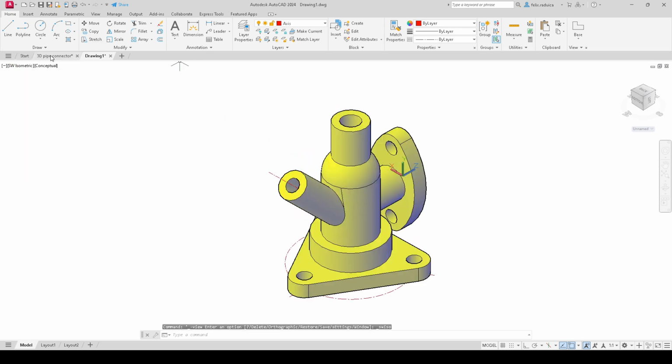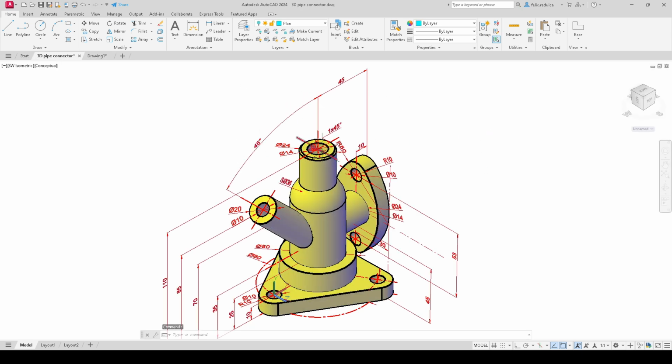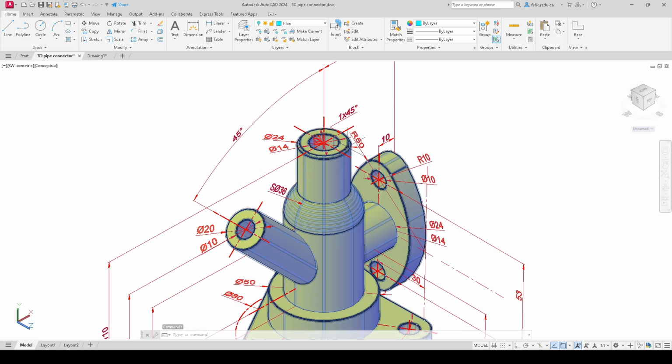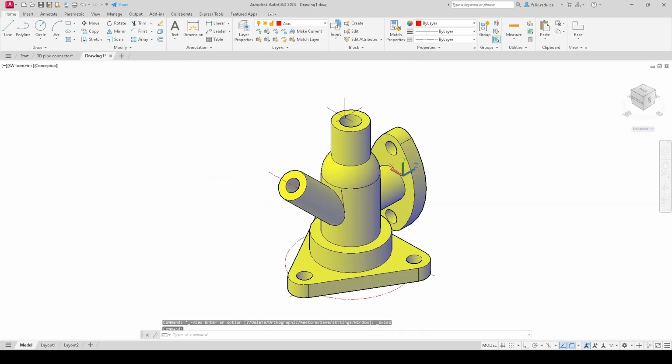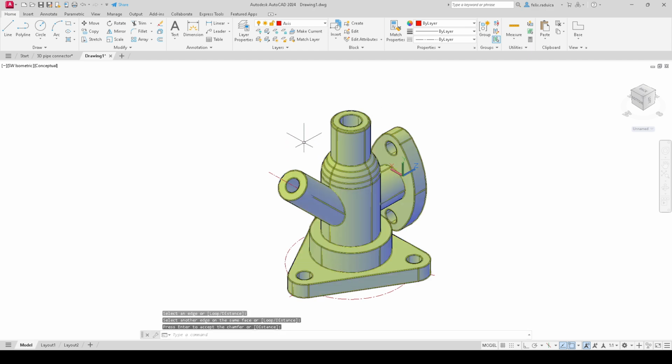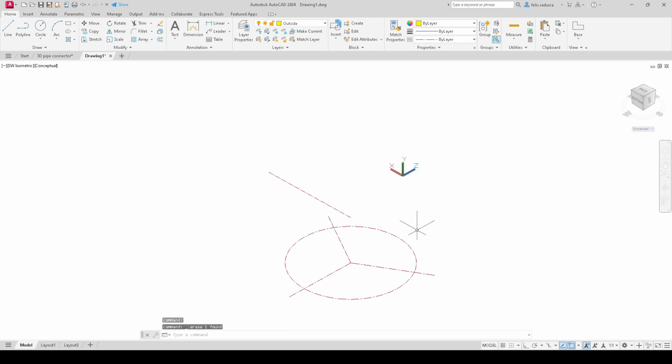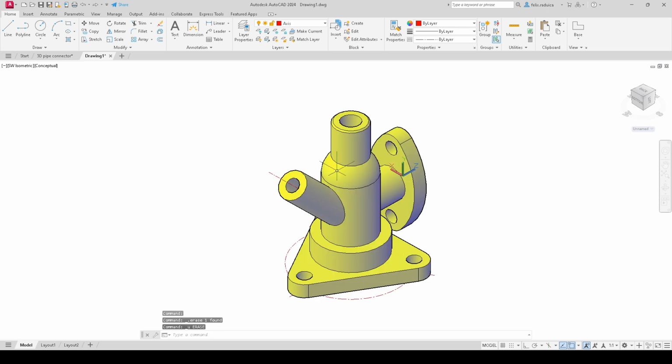What we can do next is perform the chamfer edge here, which is 1. So we can go here and perform the chamfer edge distance 1, 1, and then click on the edge there, and we have the chamfered edge as well. And now if we select this and delete it, it's only one body, so it will disappear.